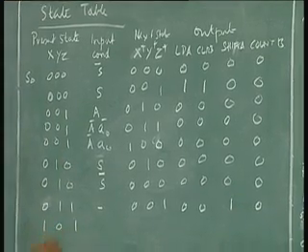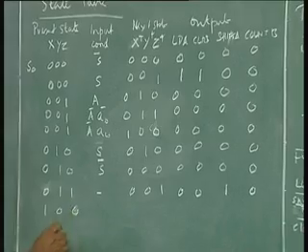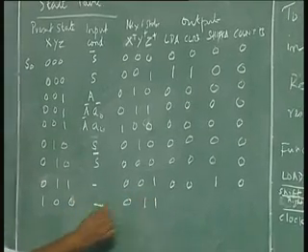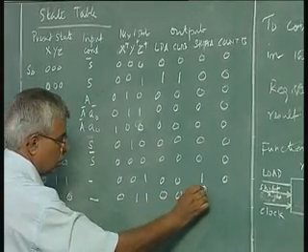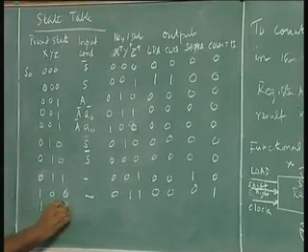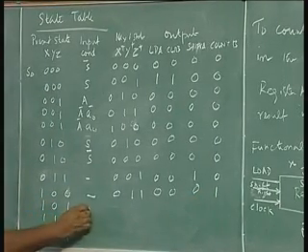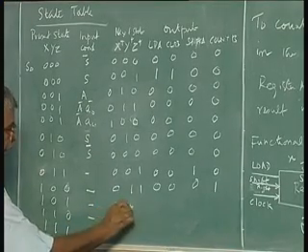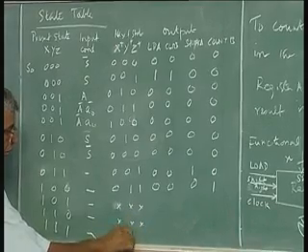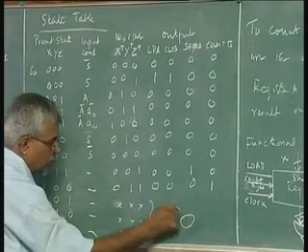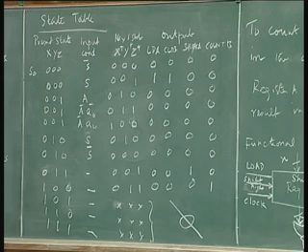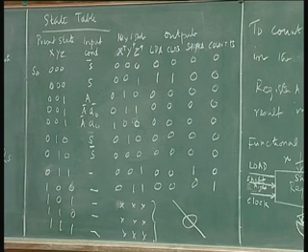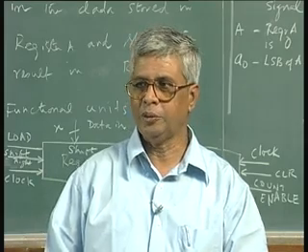1 0 1, 1 0 0 without any condition, it goes to 0 1 1. 1 0 1, 1 1 0, 1 1 1, not used. You can put don't cares, and all the outputs make 0. So, you can implement it using mux as an example. Use muxes and 3 flip flops, D flip flops and mux solution.